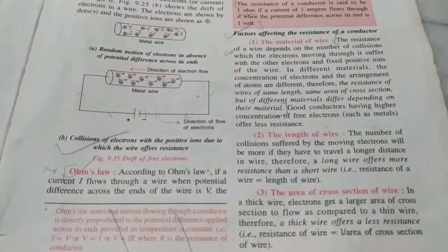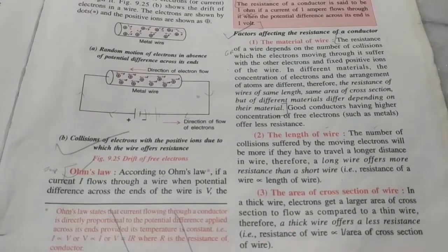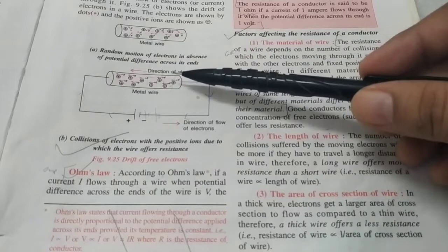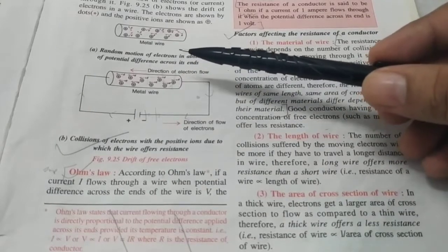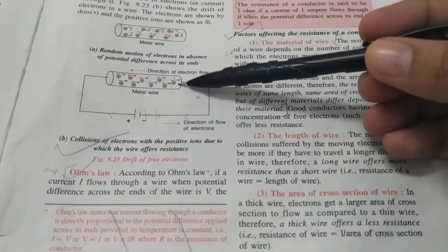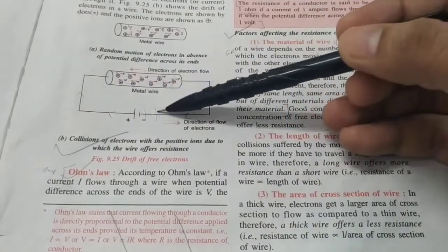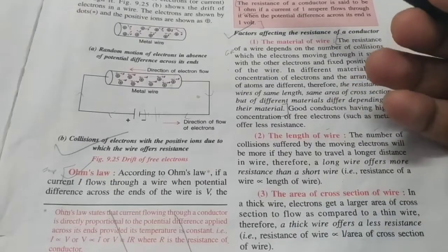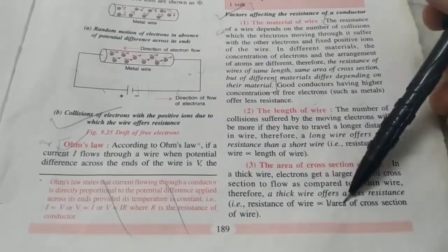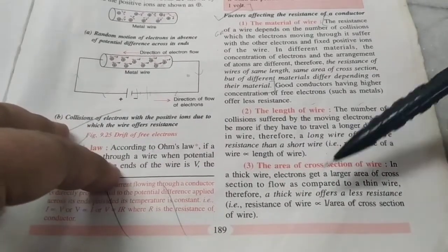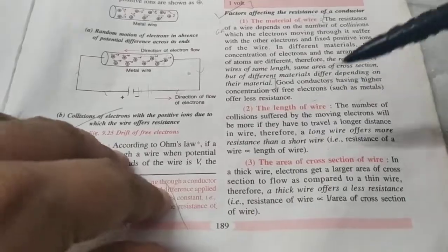Now imagine again you are driving on a road. If the road is narrow, then there will be a lot of resistance or traffic congestion you will face. On the other hand, if the road is broad, then you will be able to drive with lesser resistance in your journey. Similarly, if the wire is thick, the greater cross-section area, resistance is low. But if the wire is thin, less cross-section area, resistance is more. So you can see it's inversely proportional. If the area of cross-section is doubled, the resistance will be halved, assuming that all other factors are same.